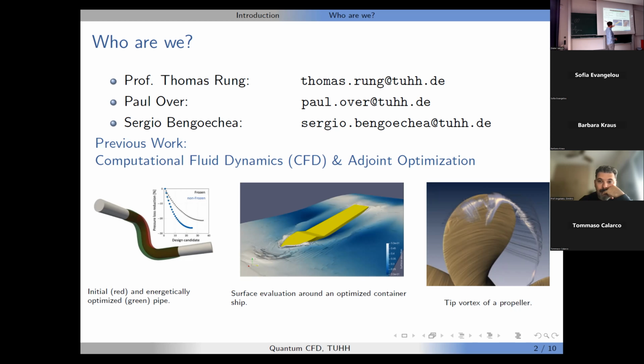The second idea would, of course, be multiple physical flows with different densities, so we have water and air and the ship cruising on a wavy surface, which is also quite hard numerically and requires quite some computation. The next one is a really high resolution case where we like to cover cavitation, a sudden decrease in pressure, in order to then maybe continue with shape optimization of that propeller or other things.